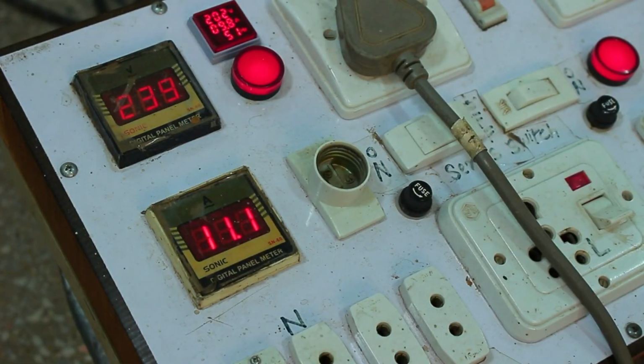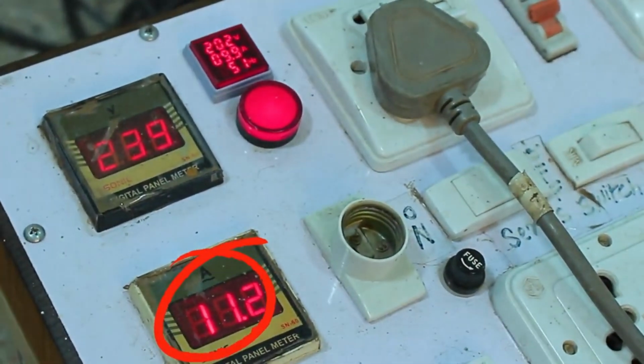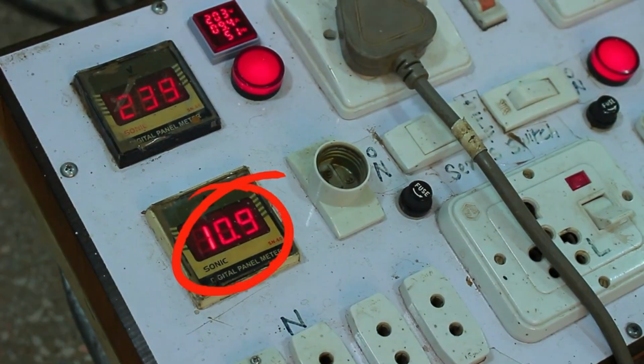At the moment, it has reached its maximum current. It went up to 12 amperes, and then the amperes started decreasing. Gradually, they continued to decline. It went up to approximately 12.5 amperes. Now the amperes are starting to increase again. So the amperes in this unit are fluctuating in this way, which should not be happening.